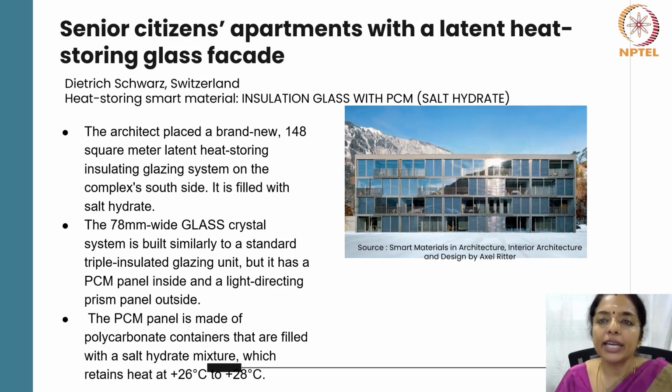The initial solution involved pure paraffin in transparent hollow plastic blocks used as latent heat storage facade elements on the south side of the building for the zero energy house. In contrast, for this project, a salt hydrate was used as a PCM due to fire safety reasons.